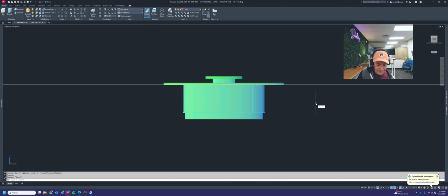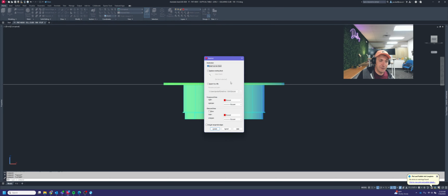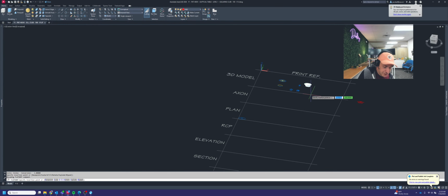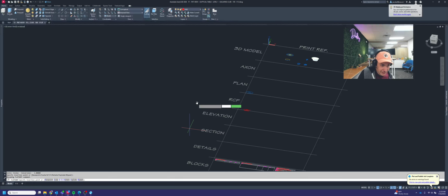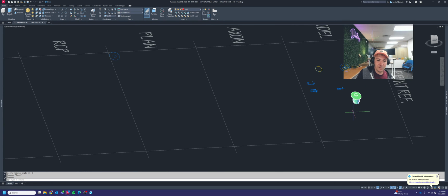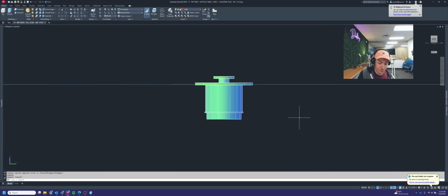All right, so let's do our flat shot here, looking at the side of our table, and make sure that, again, by layer, obscured lines is off, and by layer, you can hit create. And then I had to hold down shift and my middle mouse button to rotate my view again, but I'm going to drop that somewhere over here for now. X scale factor 1, Y scale factor 1, rotation angle 0. And this time around, what I'm going to do is make all my elevation views and then explode them, check out my line weights, and kind of work around it that way. So flat shot, again.